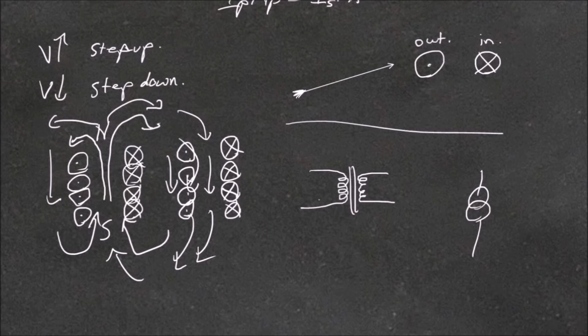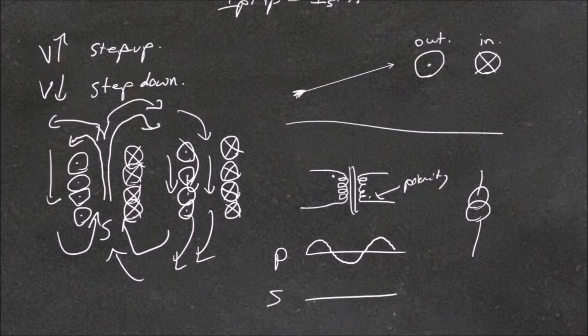So if you consider our first drawing, you can see that if you move both coils to the same side of the transformer core, the coils were in the opposite direction. So this causes the output current to be in the opposite direction, or if you like, a 180 degrees phase shift. So on a drawing, that would look like this, where these little dots are your polarity. So this 180 degrees phase shift means that your primary, if it has an input like this, will result in the secondary having an input which is 180 degrees out of phase, so each point is the opposite.